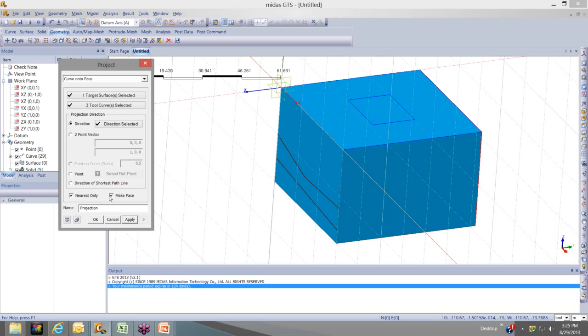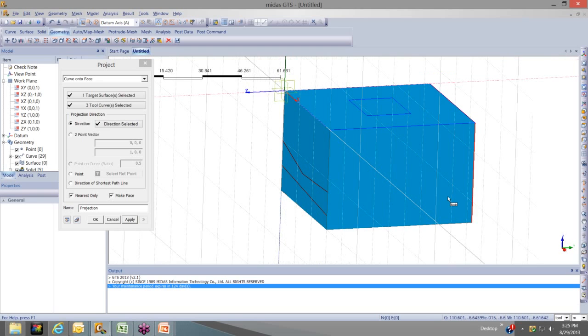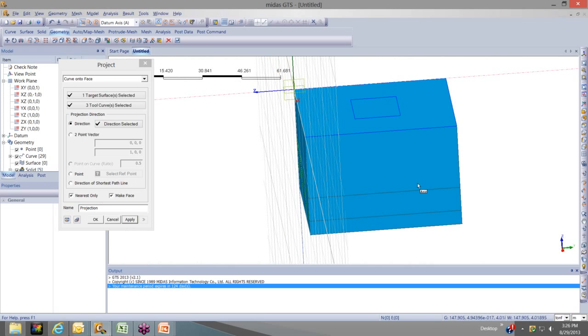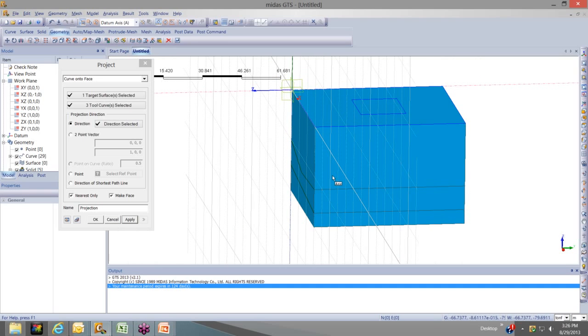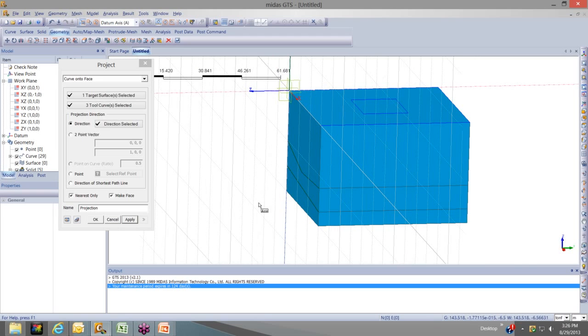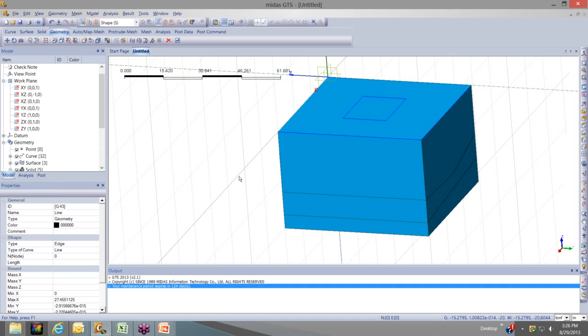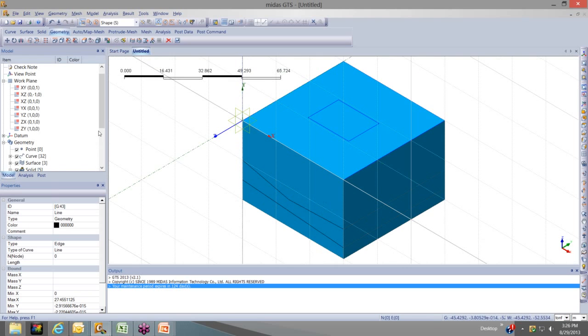This is particularly important because if you don't select this option, these shapes will just be imprinted onto this face, but there won't be an actual frame with a surface in between. Let me show you what it looks like. But first, let's take a check. As you can see, the curves are being projected while also having this line here that represents the frame. And within that line, there will be a face or a surface that we'll use to cut our soil layers. So that looks good. Click Apply.